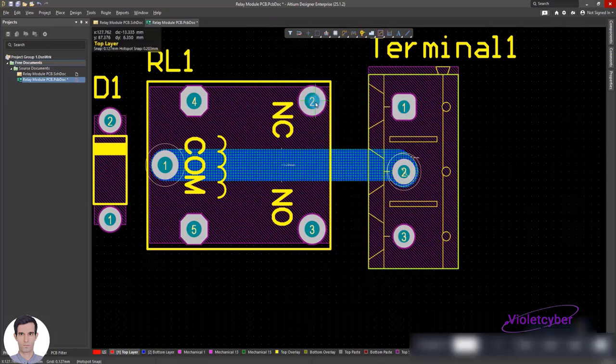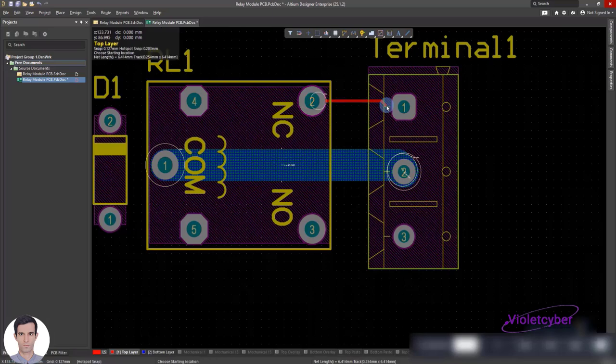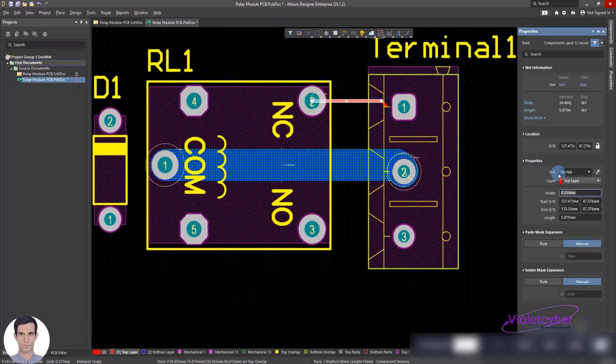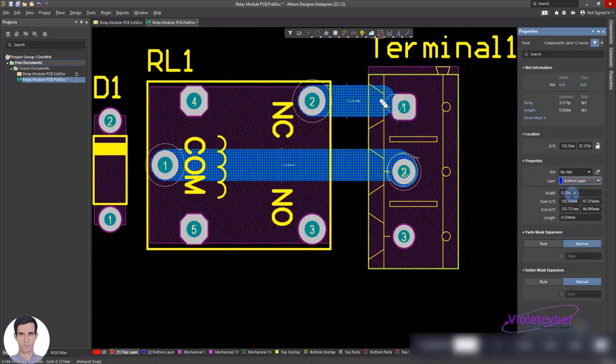That is, right-click and then here, because the mouse cannot pass the base. So when we get close to the base, we click once, right-click again, release the track, and we divide this path. We convert the layer to the bottom layer. Here, I'll set the thickness to 2.5 millimeters. I'll copy this. I'll keep it in memory so I don't have to write it every time. So, this is it, and I have this check mark left.